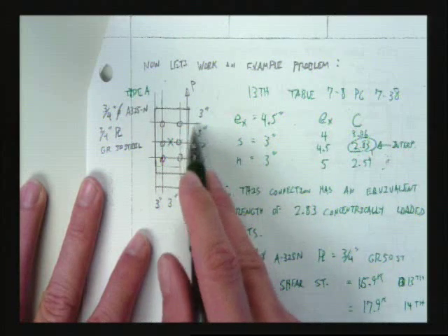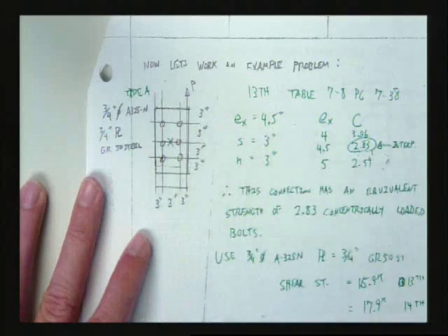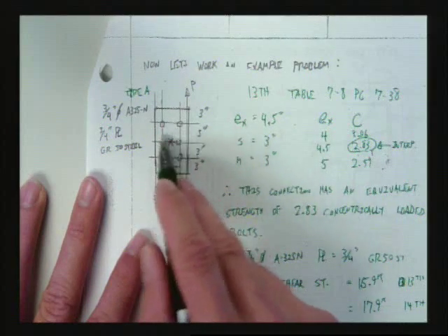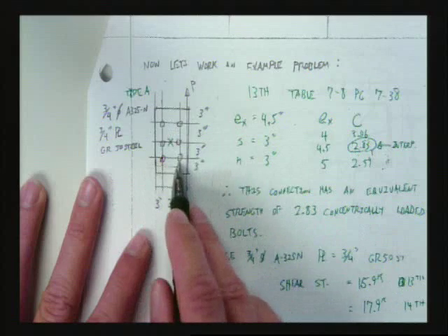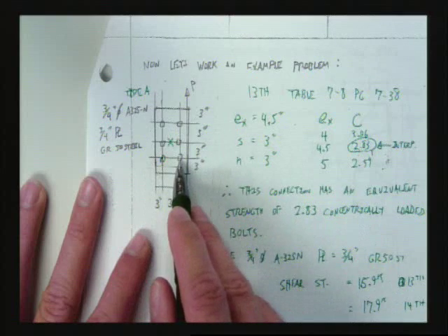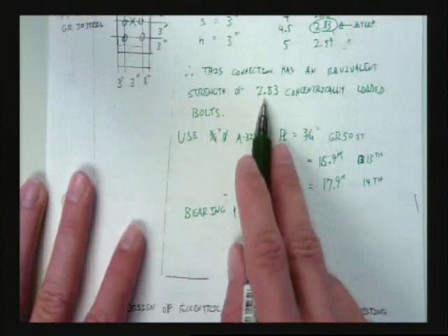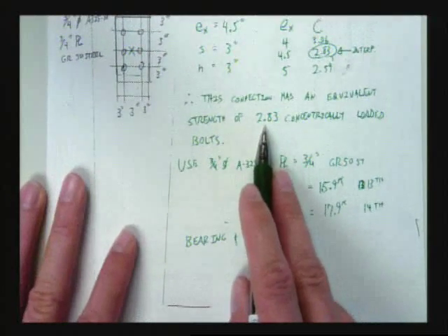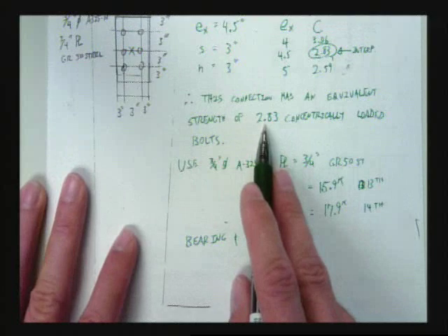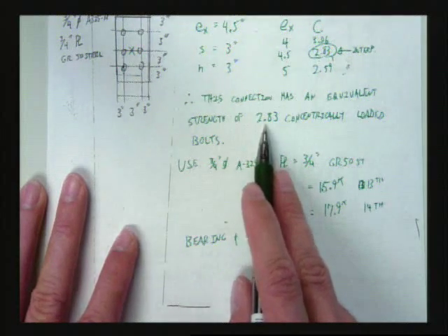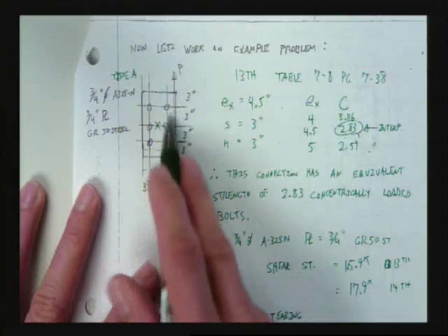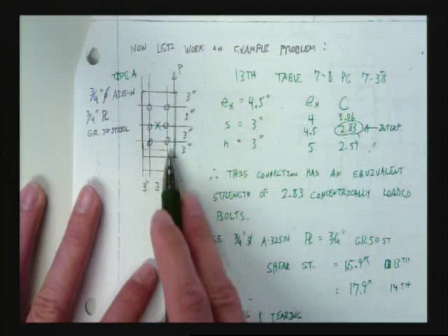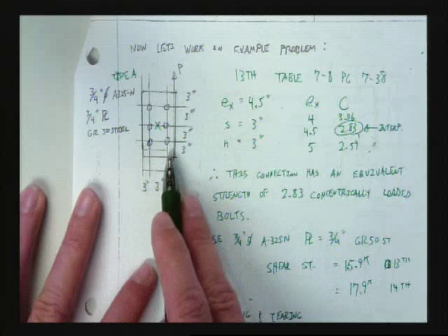We're going to pick the one that's the minimum L sub C, because technically you could do a bearing and tearing calc for each line. You could come up with a capacity for each line. But let's be honest, we've already done some lumping here. We turned 6 into 2.83. I'm not so comfortable with going back and doing some weighted average on what the bearing and tearing capacity is per bolt. You know what I mean? I think it's just time to be conservative.